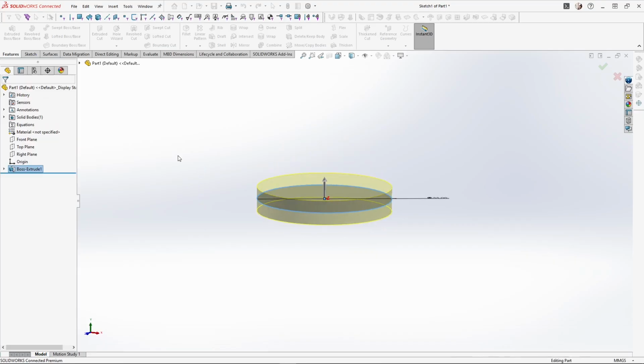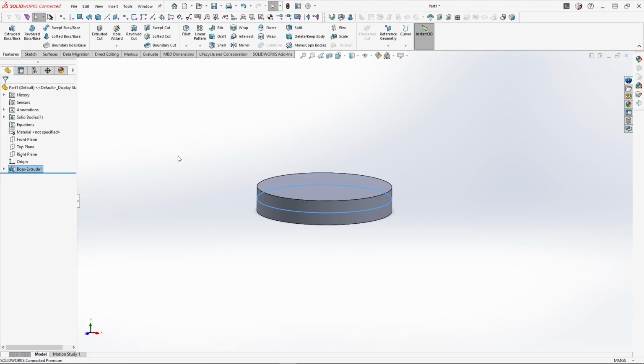All of the coins have been designed to be larger than 32mm in diameter. A standard small part cylinder which is used in toy safety is 31.7mm in diameter, so anything larger should be safe. I will demonstrate the tube later on. I have the tube modelled in SOLIDWORKS, which I use when I design other toys with small parts.